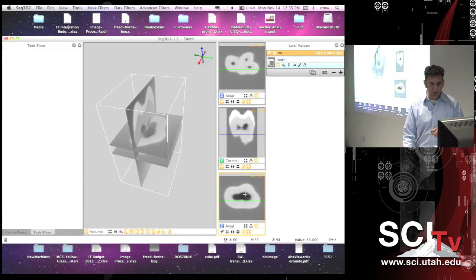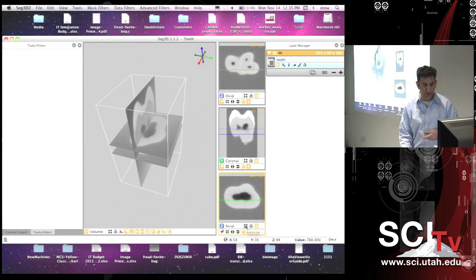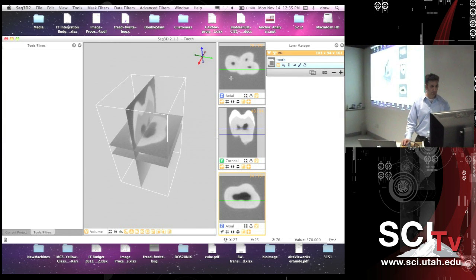And you do have complete control to zoom in. So shift right mouse is zooming, and if you get lost, you can always just auto view back in. That's what this is showing. Okay, so those were all of the controls for the slice view window.